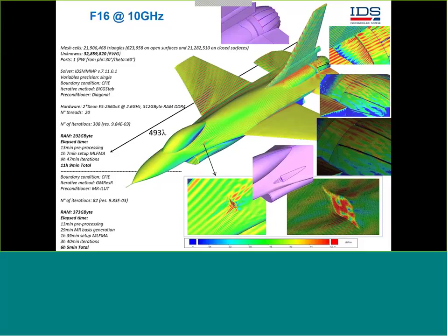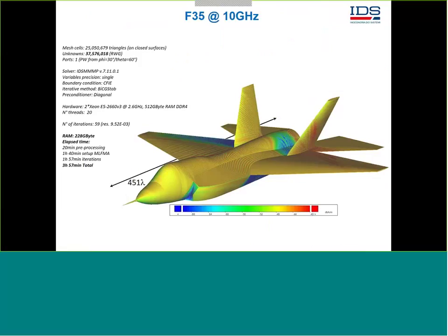Usually asymptotic methods are quite good, but in that case the user must be the driver. If we give a mesh model to the full wave engine, in that case we will always get the best result. Of course, it's time consuming and physical memory consuming, but it's the only way that we have to reach a very high fidelity, very accurate result.